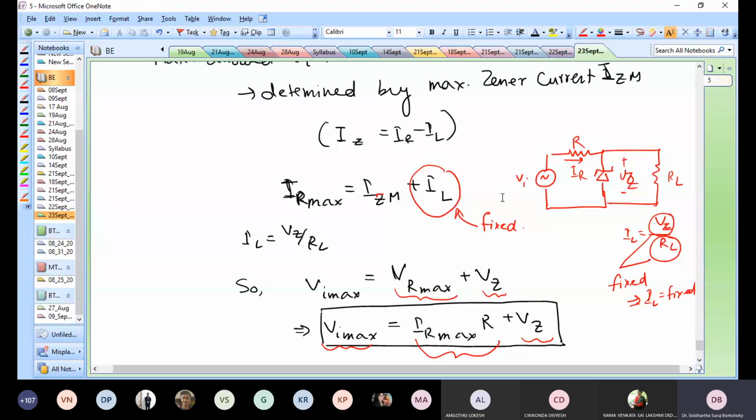The only thing to keep in mind is whether you should put a voltage drop of 0.7 volts, and in what direction, for example. When you're doing a regular diode analysis, that knee voltage, where do you put it in your second approximation? These sort of things you will have to